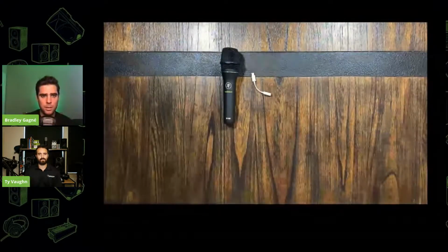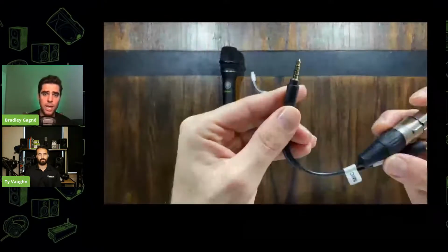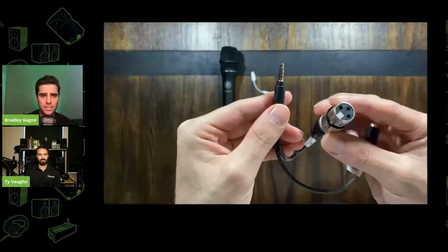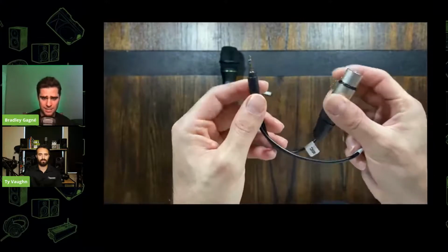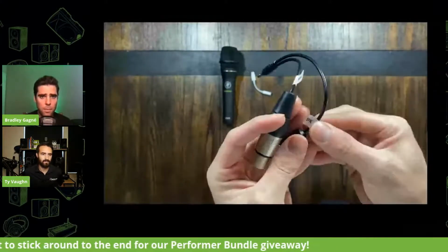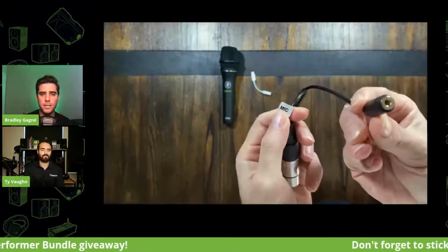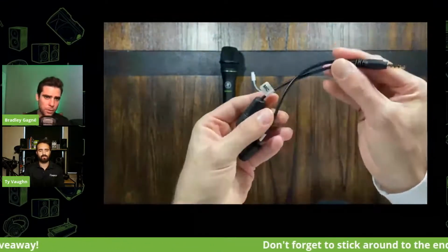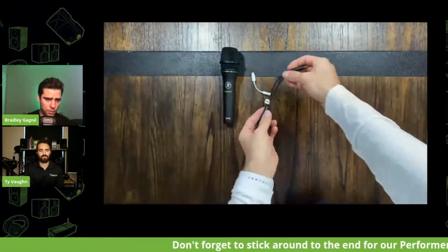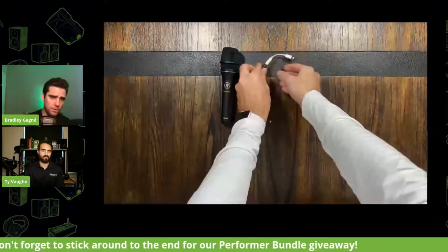You're going to need, this is one of the most important cables, the splitter cable. This is a TRRS. It's tip, ring, and sleeve. Gives you left and right and the microphone. So you've got our microphone channel and our speaker channel, and it's split from that TRRS cable. And that's going to allow us to send the output of the phone and then also route the audio back in to the phone. So you connect the adapter there.